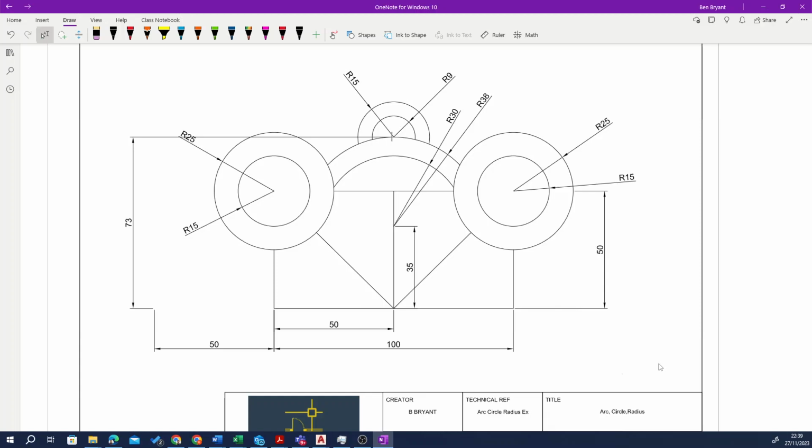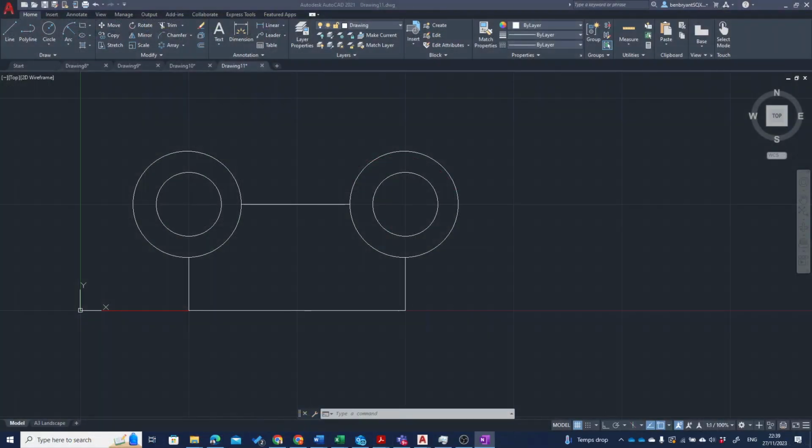What you should realise is this is also another 2 circles that's referenced around this point. Now this point is 35 up from the centre of the rectangle. Okay, so again, I'm just going to draw a line. Find the intersection point, drive it up.